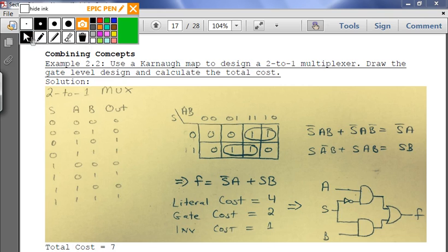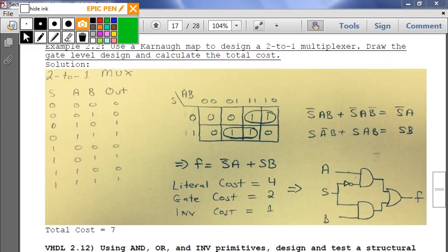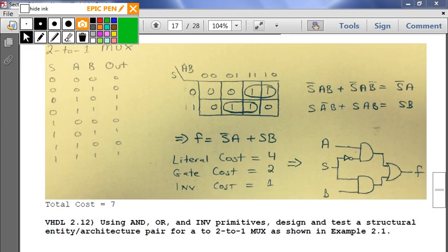Would there be a race condition at the 1, 1, and 1? If you don't properly buffer it, yeah. So that becomes an issue. Sometimes you can have the inverter signal delay, a very small delay. So what you could do is you could have a buffer here, and you would actually delay it. For example, in an AND gate, one way you could do this is to have a NAND gate and inverter, and have the inverter serve as the buffer. So that's how you do it at the CMOS level.